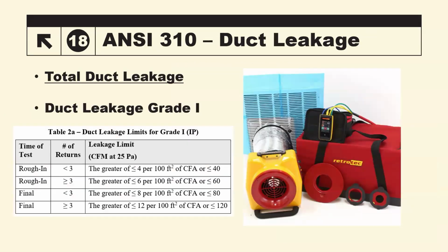And then total duct leakage is step two. So we've gone through that design review and now we've just got into step two. So total duct leakage is required for HVAC grading. Leakage to outside is not allowed. If you're not familiar with that phrase, LTO and TDL: total duct leakage is just using a duct tester and you're doing the whole system either at pre-drywall or at a final. And then leakage to outside is when you're doing a blower door in conjunction with a duct tester and you're coming up with the number of what's leaking outside of the envelope.